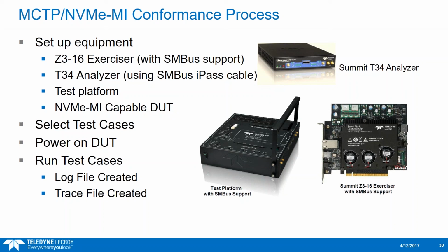You need to use a T34 analyzer. The T38 analyzer does not support the SM bus testing. You need a test platform also that has the SM bus support. It's marked on it whether it supports SM bus or not. And obviously an NVMe MI capable DUT.